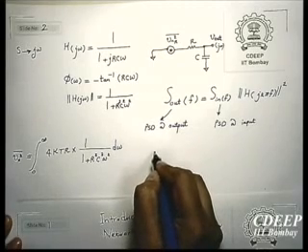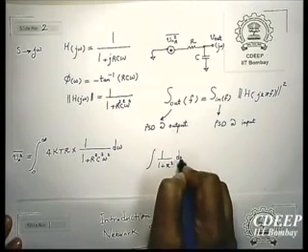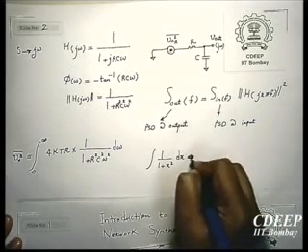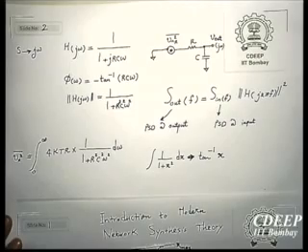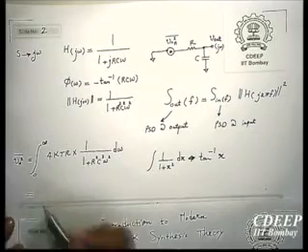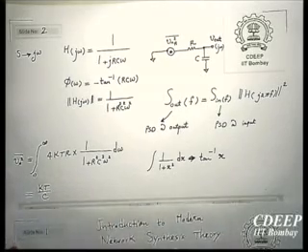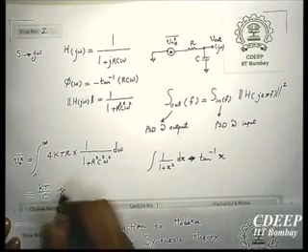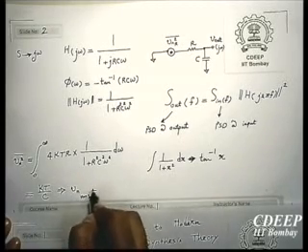So you know, this essentially gives you this tan inverse x. Therefore this part is constant. Therefore if you calculate, final value will be kT by C. And that is that famous kT by C noise.